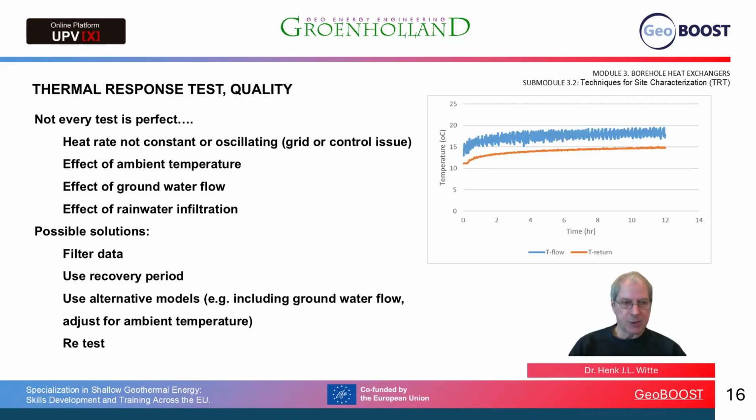Other effects that are possible are effects of ambient temperature, being low at night and high during the day, for instance, and not well insulated connections to the borehole. Effect of groundwater flow, which will completely invalidate the results because heat conduction is not the only process anymore of heat transport in the ground. And we can have effects of rainwater infiltration, for instance.